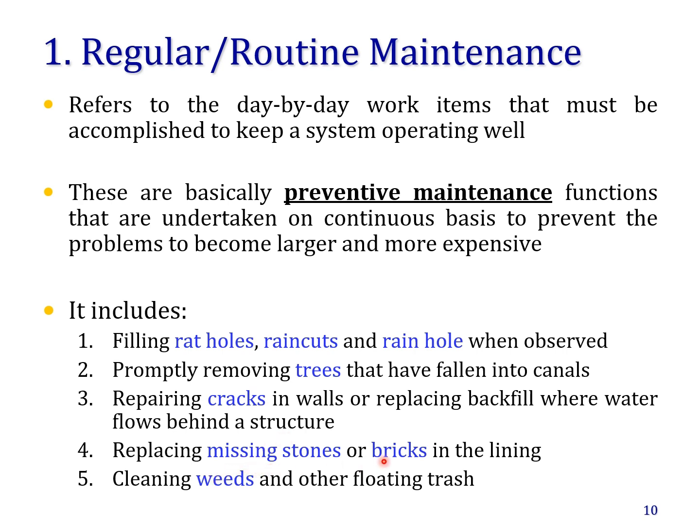Replacing the missing stone and the brick in the lining, cleaning the weed or any floating trash in the canal. All these are everyday maintenance or regular maintenance things. And there is a staff of the canal whose job is to patrol along the bank of the canal and see if there is any such small problem. They have tools and they should fix it right there.